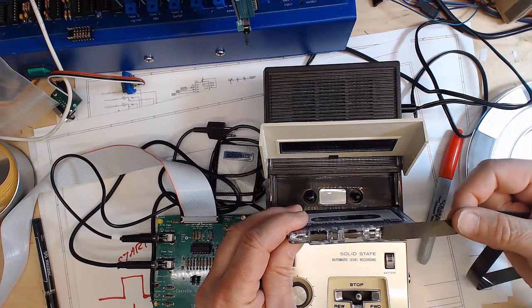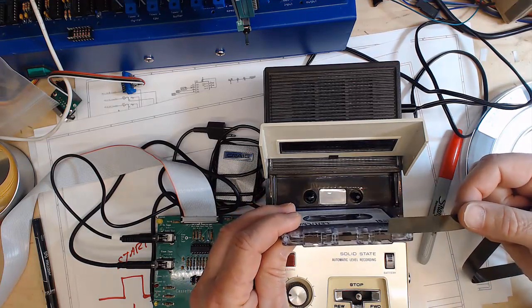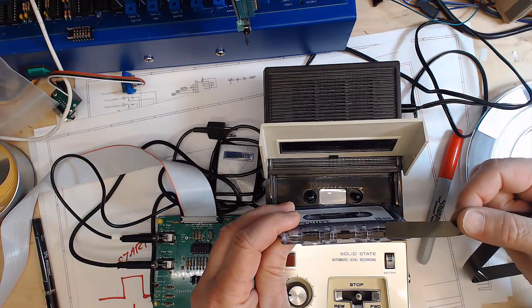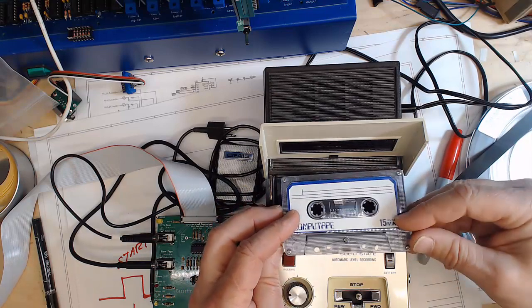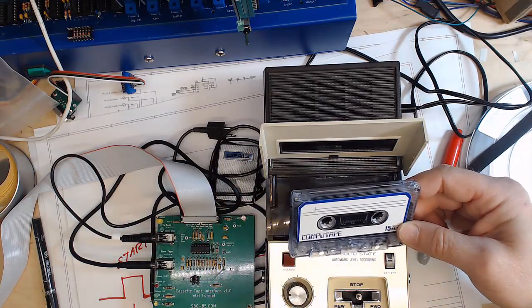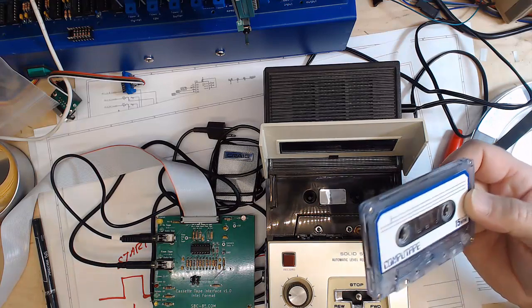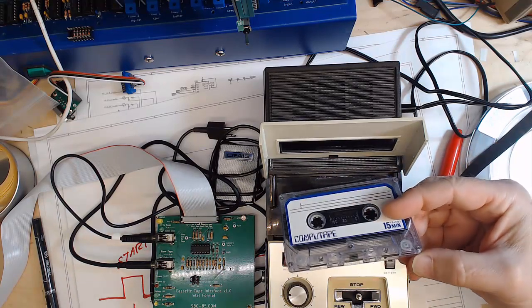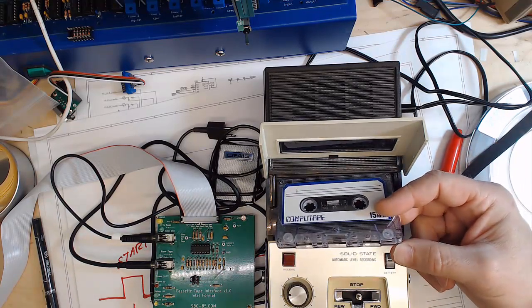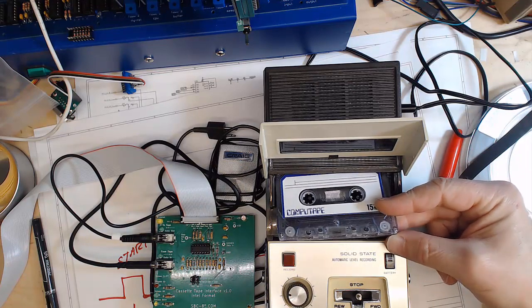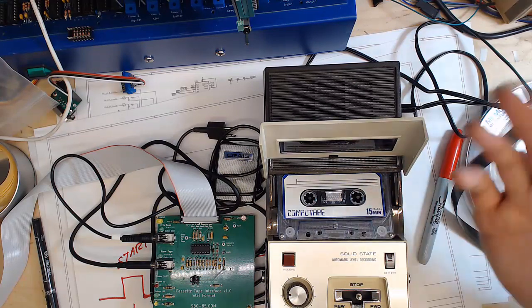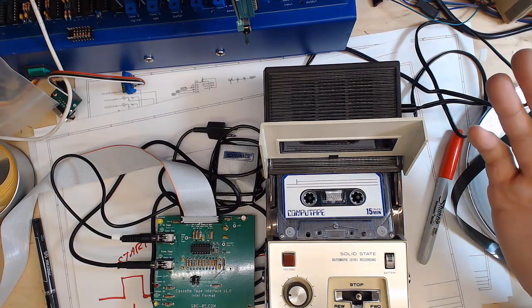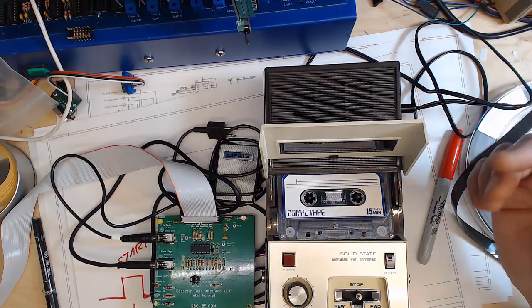So obviously on the compact cassette, there's not going to be enough width of the tape to be able to store this in parallel format. So it's going to have to be a serial format when it's stored on this tape. The other problem you have is that the tape player is designed for audio frequency response. It's designed to get rid of noise, and it's got filtering, and so everything in the electronics in this is essentially AC coupled and filtered for audio range, up to maybe 20 kilohertz.